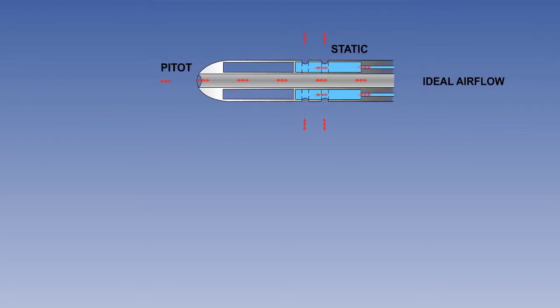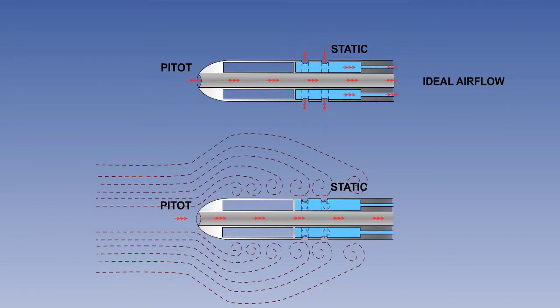Ideally, the airflow around a pressure head should resemble the airflow shown here in diagrammatic form. However, if the aircraft is moving, a suction effect will be created which will cause the static pressure sensed to be lower than the ambient pressure. As the speed increases, the airflow in the region of the pitot heads becomes turbulent and this under reading becomes greater. How great the error may be depends on the location of the pressure head and the speed of the aircraft.